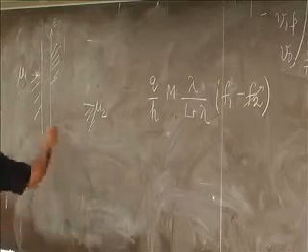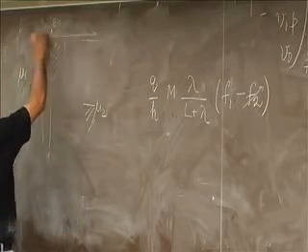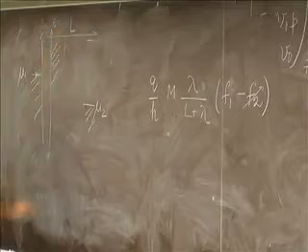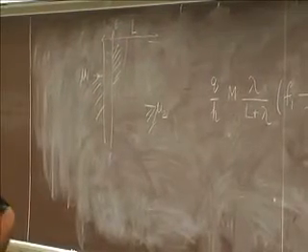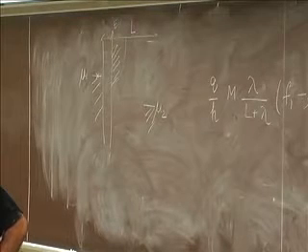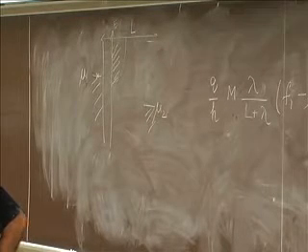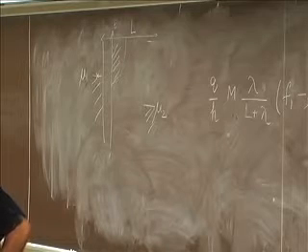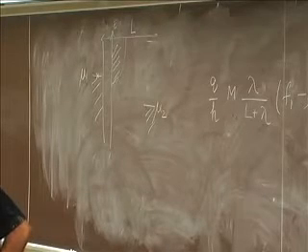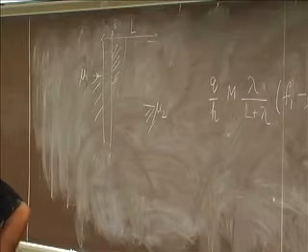Because although the length of the device is some length that based on the low field current, you might have thought that it is 50 mean free paths. But when you look at the saturation current, it looks like a whole lot less. Looks like it's only 10 mean free paths. And the question is, why is that part of it?